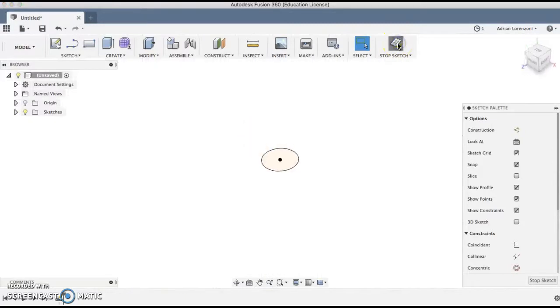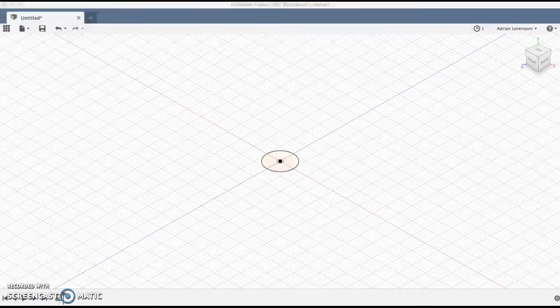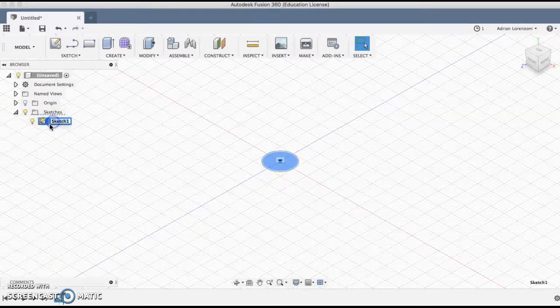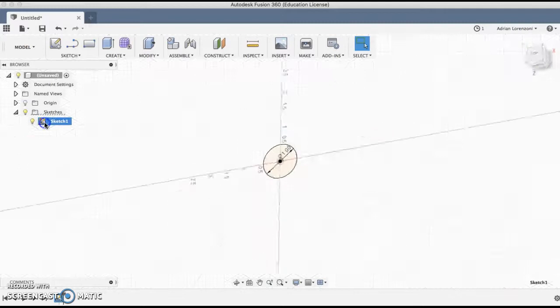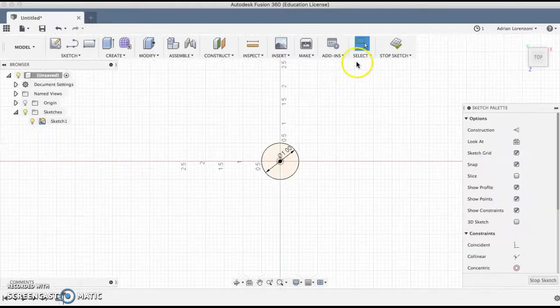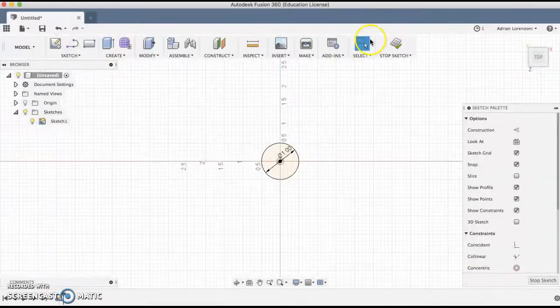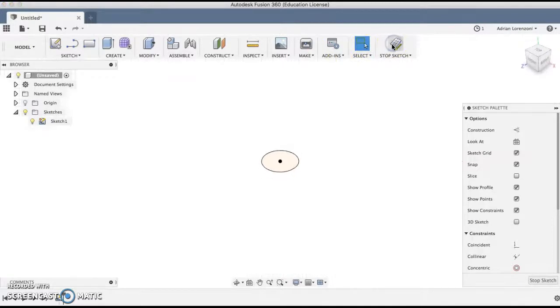So we're just making a cylinder at this point. Okay, we're starting simple. Once the sketch is done, then you've got to actually make it into a 3D object. Now you can see in our left tree here we have this sketch. So if you ever want to edit it again, just double click the sketch here, and that allows us to edit it. Another way to do it, which I like better, is the timeline. Just down here, we double click this, that allows us to edit it. Okay, and we'll look at that in more detail as we go along.